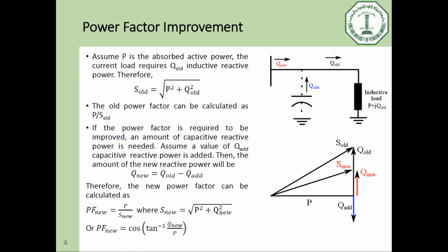However, for the supply at homes, the supply should be constant all of the time, and we call it grid voltage or infinite bus. And we refer all of the time to the infinite bus. Infinite bus means constant voltage and constant frequency. And this is the aim for any grid. You should keep the frequency and voltage constant. However, the current is load dependent. The current changes according to the value of load.